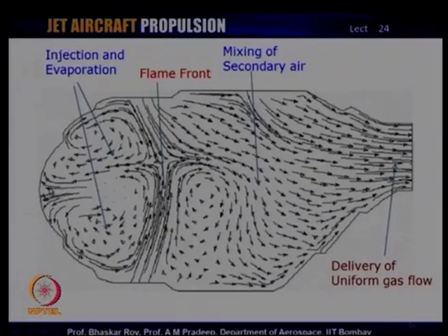As it comes inside through the swirler, which we saw, the actual velocity is reduced to nearly 30-40 meters per second, and then through the recirculation, as we are seeing here, the forward movement or the actual velocity is brought down pretty close to something like 4 to 5 meters per second, because that is where the flame can be sustained.